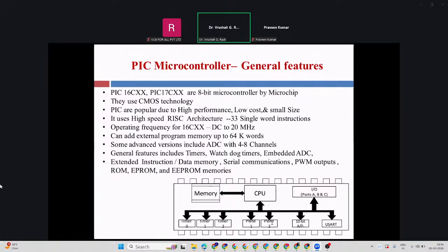Why do we need pulse width modulation? Whenever we have to think about speed control, we have to think of pulse width modulation. Whenever my microcontroller is driving some mechanical part where I have to deal with speed control, I need pulse width modulation. By changing the width of that pulse, you can control the speed of maybe a motor, whatever it is.